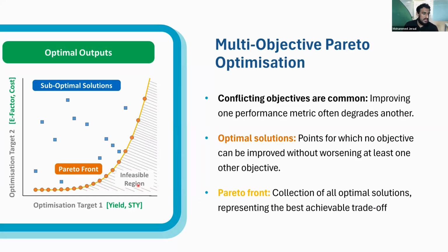So even though at first glance, it might be easy to say that this experiment here, or perhaps this one, or this one is the best one, because it kind of gives you the best compromise between them. But you might have a situation where you're just interested in having the best yield regardless, and you might be willing to take a small compromise in cost in order to get that increase in yield. There might be other processes which are just hell-bent on reducing costs, and as a result of that, you might be willing to compromise yield in order to get that cost. So with Pareto optimization, you don't have to make that decision now. It will just find the optimal trade-off between these two variables, and you can make the decision later.